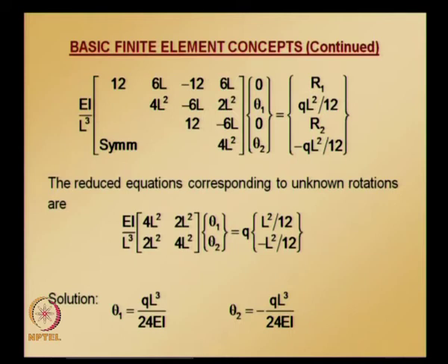And now since we got all the nodal values, that is we know V1, and now we calculated theta 1. Similarly we know V2, and now we calculated theta 2. Now we are ready to solve for the element quantities: displacement at any point in the element, moment at any point in the element, shear at any point in the element.